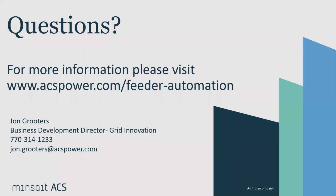And of course, for all of those events with regard to disabling or enabling FLISR on the system, the operator is notified of all those things as they happen through standard event and alarm messages, so that they're constantly aware of the status of the system. And then those alarms and events can be sent upstream to the SCADA system that the system's connected to.